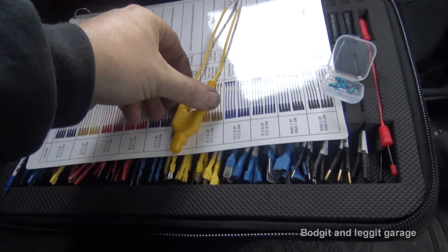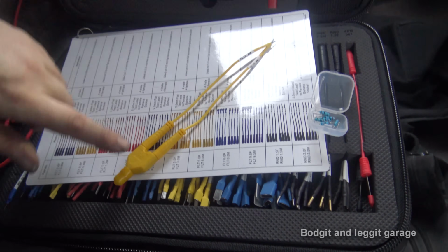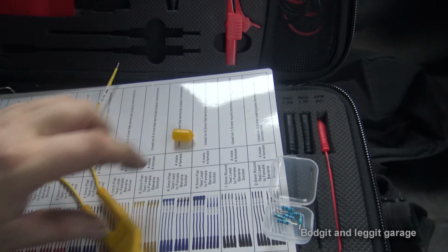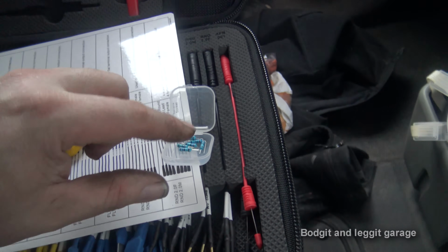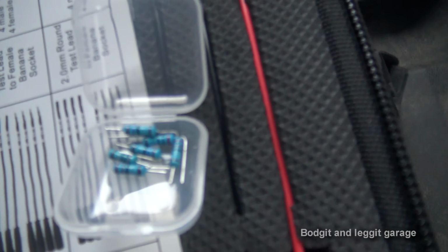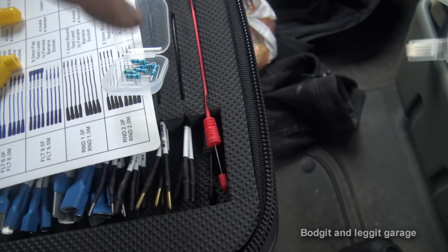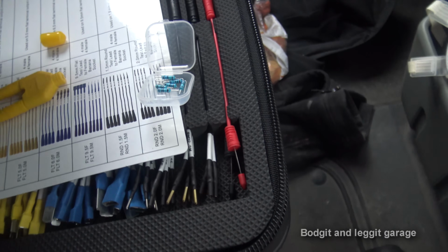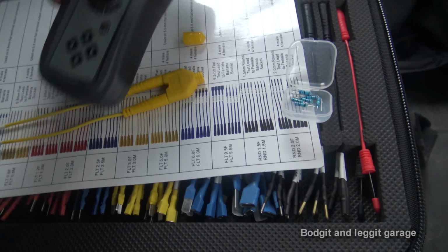Okay, so first thing we need to do is select the right pins to put into our airbag system and to select the right adapter. We have two adapters in the kit here, and what's really good about this is you can put different resistors into it, and you get some resistors with it. Now, if you're unsure, on each resistor is a band and they're different colors. You can get an app on your phone so you can put in the bands and you'll know what the resistance is. But if you're not sure and you don't want to do it that way, just get your tester, turn it on to ohms, and we'll test.